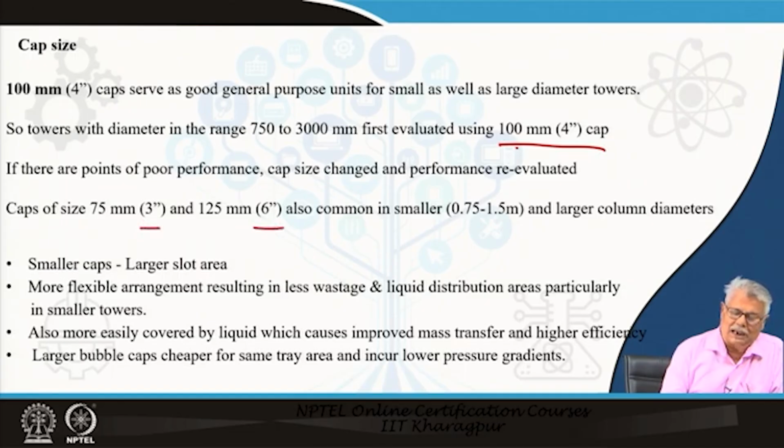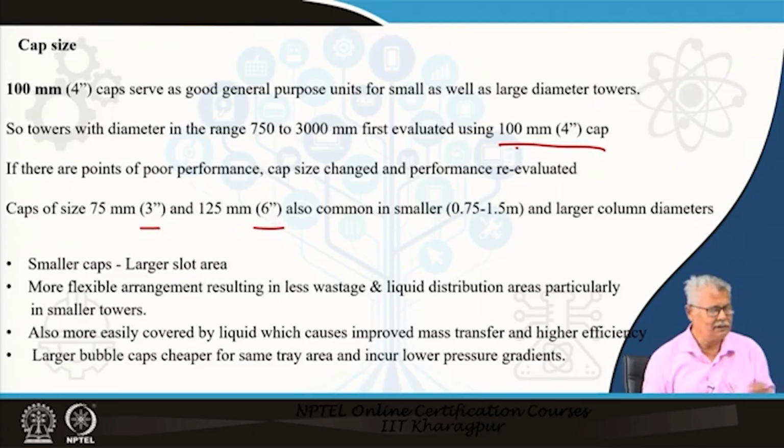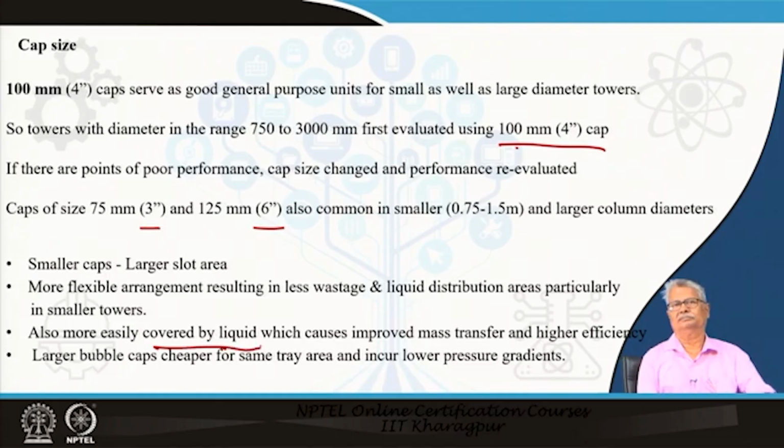Smaller caps and bigger caps are also in use in the smaller and the larger diameters. If you have a smaller cap, in proportion to the cap size, it will have a larger amount of slot area. If you are using smaller caps, you will have a more flexible arrangement of laying it out on your tray, but you will require a larger number of caps. Now, smaller caps are also more easily covered by the liquid. That is something desirable because it helps mass transfer and leads to higher efficiencies.